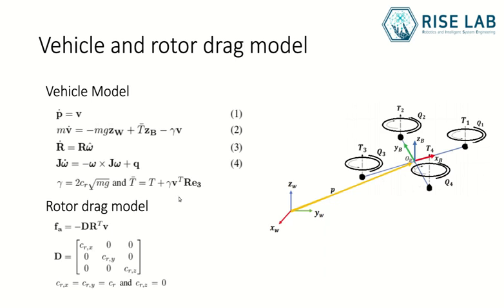It is possible to simplify this model to include a T-bar thrust, which now represents an augmented collective thrust, augmented by this expression, basically coming from the induced thrust produced by the motion of the vehicle, and a simplified drag term. Here, gamma is a constant proportional to the rotor drag constant and the square root of the mass times the gravity.